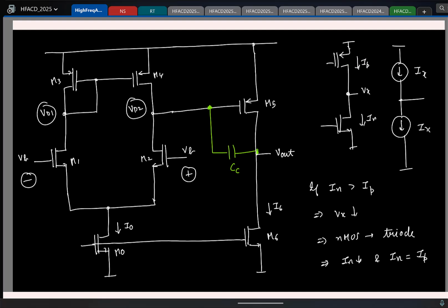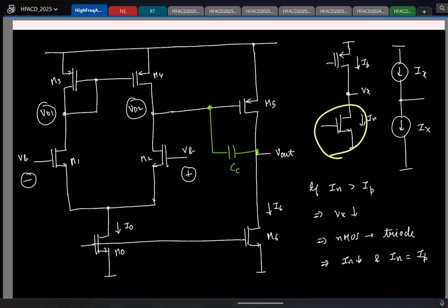Okay. So in practice, you should never have a case where you have two independent current sources connected in series like this. You should only have one of the current sources independently biased, while the other current source has to be biased based on this one. So there should be some feedback mechanism that goes and tunes this current so that the value of this current source is equal to the independent current source. Both of them cannot be independently biased. That's the idea. Is it clear?